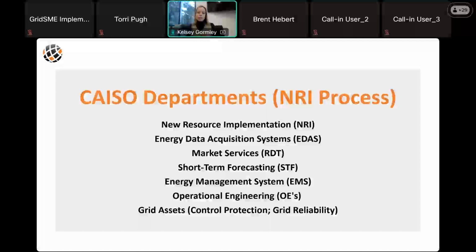They review our technical submittals, including our electrical single line diagrams, metering 3-line drawings, communication block diagrams, meter configuration forms, real-time device RIG details forms, and they conduct the pre-sync point-to-point testing with your CAISO RIG. They also monitor site telemetry prior to approving COD. We'll talk a little bit about that later this afternoon. So they're a really important group that we interact with throughout the process.